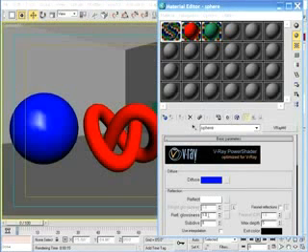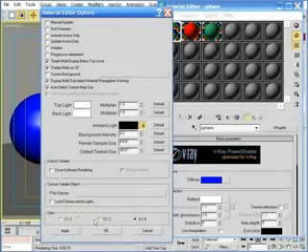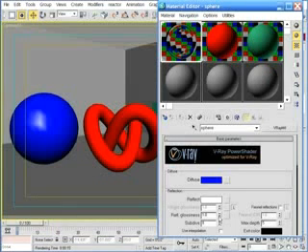With a value of 1.0, VRay makes the material 100% glossy, so perfectly glossy in fact that the highlight is infinitely small and therefore invisible. Anything other than 1.0 results in a specular highlight, and the smaller the value, the larger the highlight and the rougher the material looks.